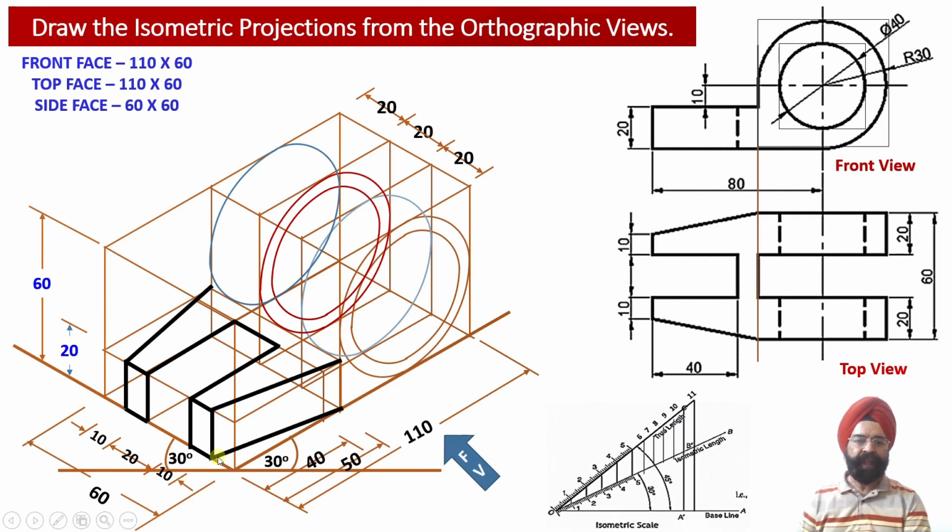So we can check this inclined portion toward the front side, and this top portion will be visible to the observer. And then this portion, that is corresponding to this horizontal element at the base and this vertical element over here, will also be visible to the observer. So the front portion corresponding to the horizontal element up to a length of 50 millimeter has been obtained.